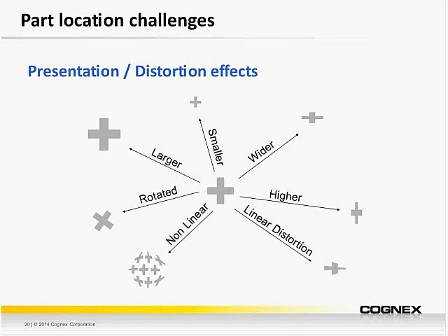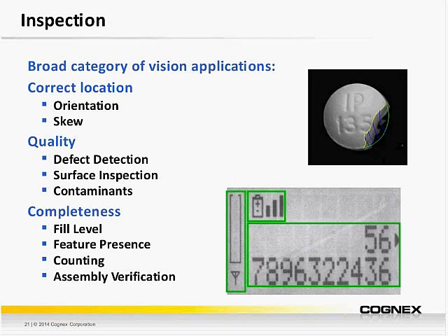Because of the vision tool alignment or fixturing aspect of machine vision systems, your parts can be facing all different directions as they go down your production line. And as long as you have a very robust pattern-matching tool, you can still locate it, fixture the subsequent vision tools properly within the image, and then run them to achieve accurate, reliable, and repeatable results.